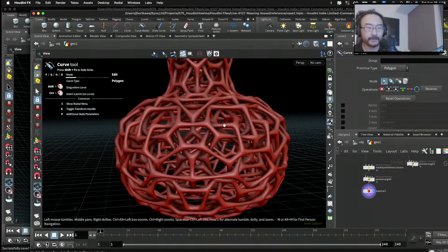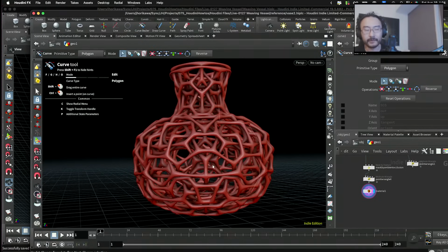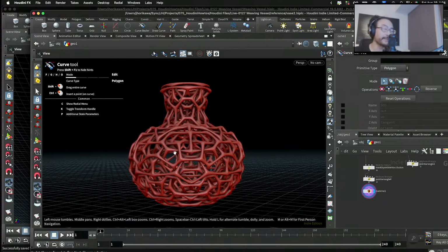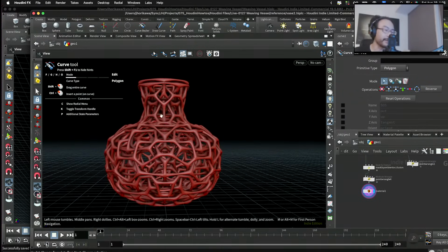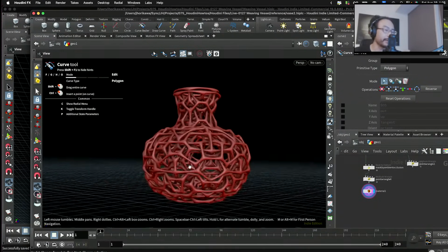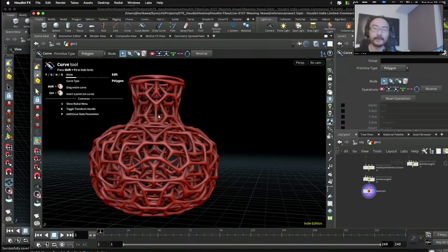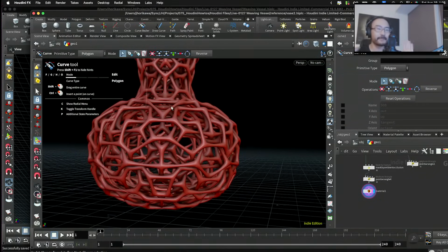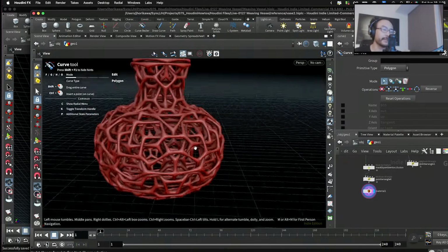And as you can see, if you look from specific directions, the geometry is mirrored. So I'm going to create this kind of pattern using voronoi as a base. If you just use voronoi as it is, it's just going to be pretty random, but if you control the point position for the voronoi, then you could get this kind of repeated pattern. And if you do this for all the layers, all the surfaces, I'm gonna get a repeated clean pattern or geometries like these.